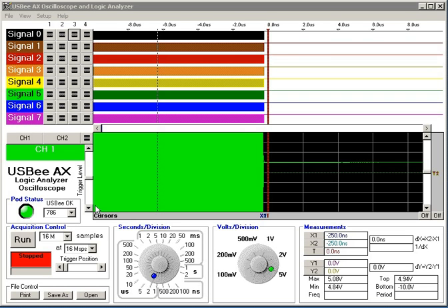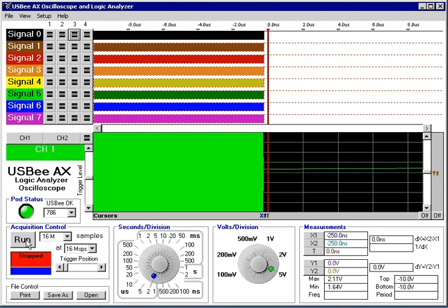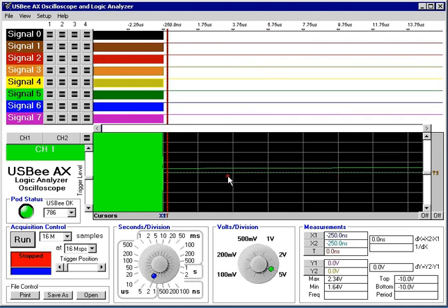What we're going to do is simply press the run button. We have one sine wave attached to channel 1. We also have 2 digital wires attached to a periodic sample, and the trace is finished. You see the stop condition here, and the wave is now captured. We are actually zoomed out. We're at 2 microseconds per division.